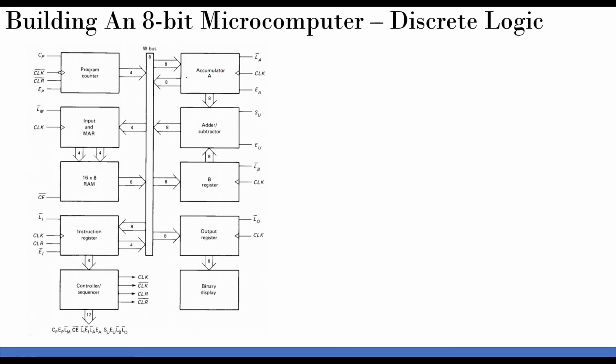So this is basically the first input, this is another input. Register A and register B are the inputs to the adder or subtractor unit, and the result also gets stored in register A, and hence register A has a special name, accumulator. Also keep a look at the control unit, which we will discuss as we discuss the working of this circuitry. But in this lecture my aim is just to introduce you to the building blocks of this circuitry. Then the output value will be stored in the output register, and that will be displayed at the output. So this is the holistic picture.